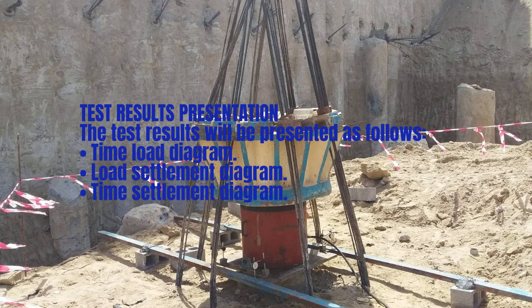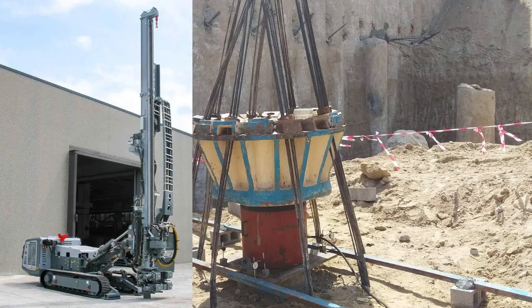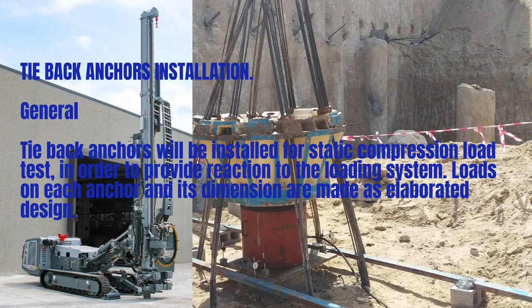Tie-back anchorage installation. Tie-back anchors will be installed for the static compression load test in order to provide reaction to the loading system. Loads on each anchor and its dimensions are made as in the laboratory design. Installation procedure: a powerful Casagrande C6 micro pile rig will be used to install the tie-back anchors.